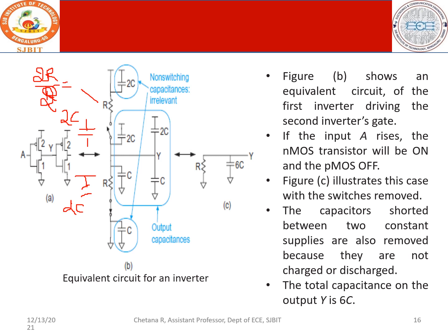Therefore, the value of R for the PMOS happens to be R. Whereas here the value of the R is R by 1. Therefore, it is R. And capacitance, since it is 1, it will be C into 1 at the drain as well as at the source. So all are pulled down to the ground terminal. This is pulled up to the supply terminal. This is with respect to the first stage of the inverter, which is nothing but the driver.